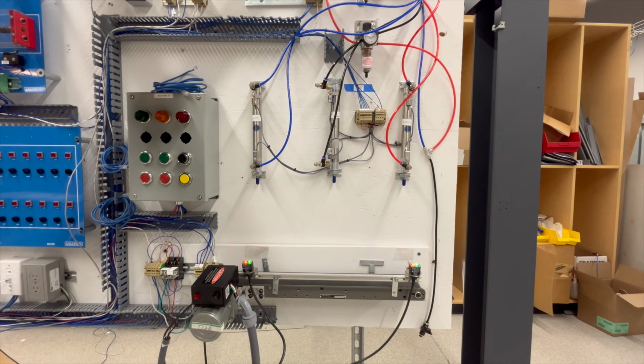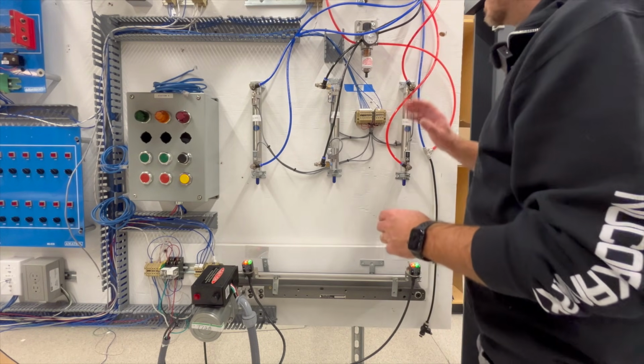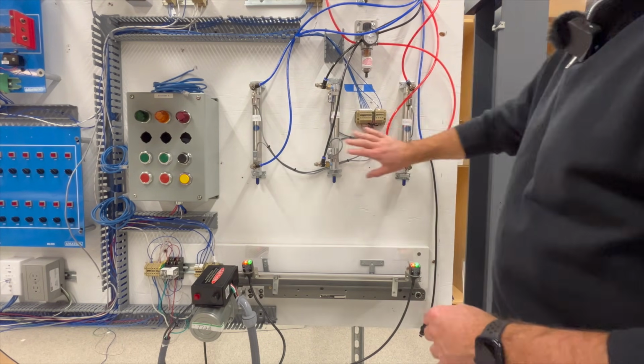This is a way you could go through and troubleshoot when multiple PLC inputs have stopped working. Look for what is common amongst them, okay? In this case, the thing that tied all of them together was the common going to the PLC, and I just traced the problem out. Now let's say all 6 of these weren't working.